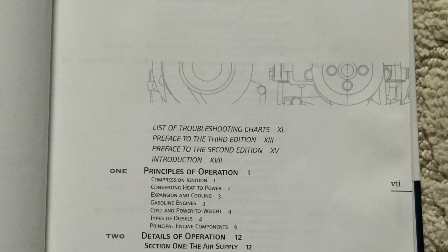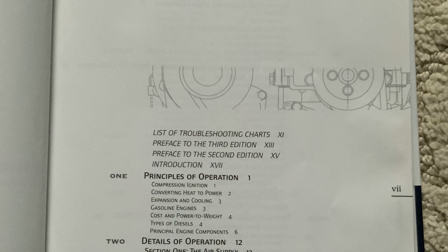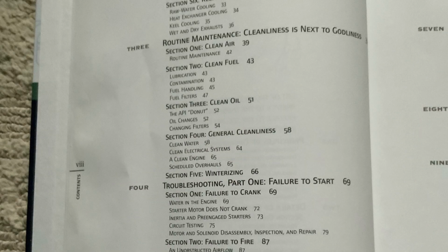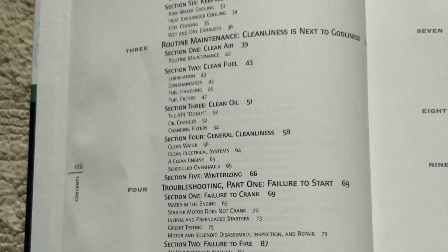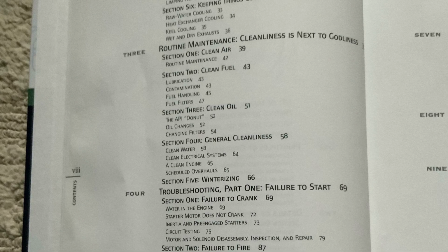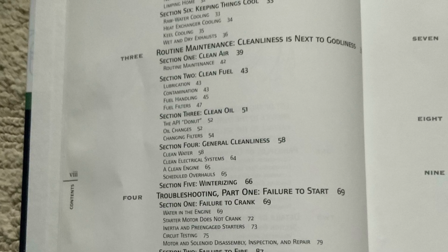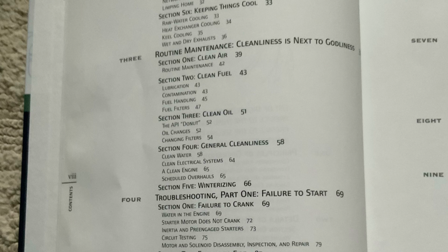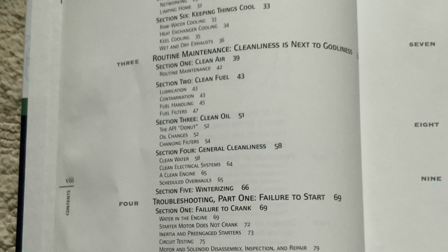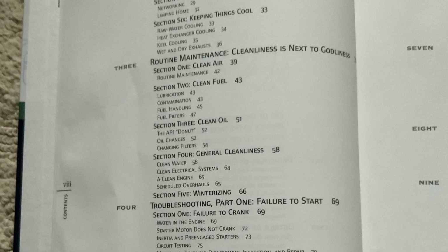To attain high enough temperatures to ignite diesel fuel, air generally has to be compressed into a space no larger than 1/14 of the original size of the cylinder. This is known as a compression ratio of 14:1. The compression ratio is the volume of the cylinder when the piston is at the bottom of the stroke, relative to the volume of the cylinder when the piston is at the top of the stroke. See Figure 1-2. Most diesel engines have compression ratios ranging from 16:1 to 23:1.